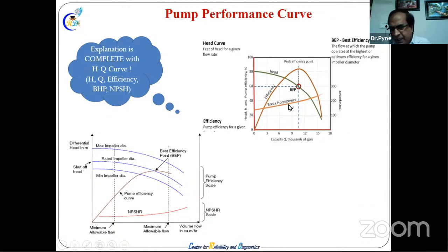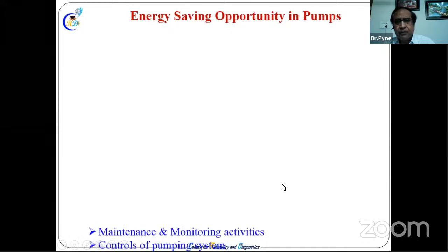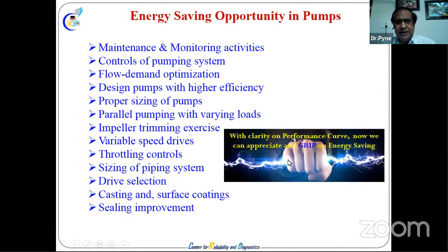Okay, because this energy curve is there. If you go here, energy is more, but your pressure requirement is less. If you want more pressure, energy is less, but your flow will be low. So all judicious judgment should be done. Impeller diameter, how it changes efficiency over time, is shown in this graph. Okay, and that means for energy saving in pumps, there are a lot of possibilities.